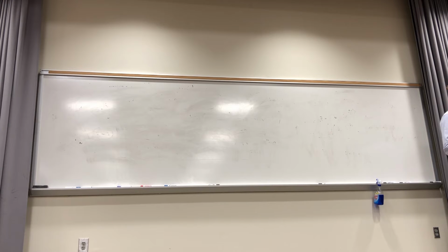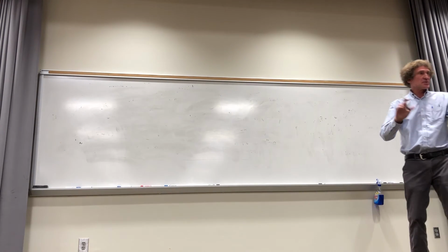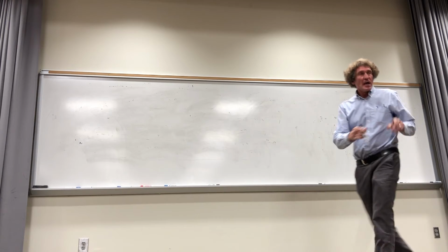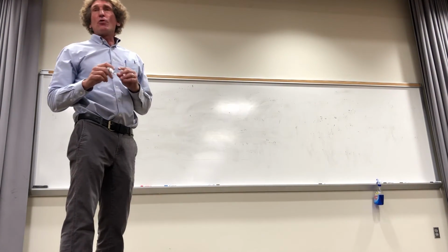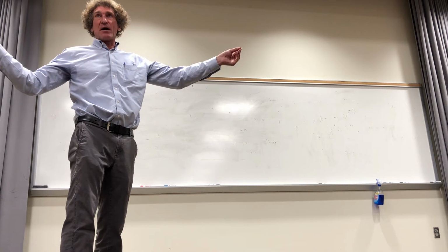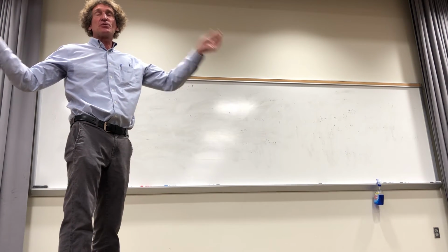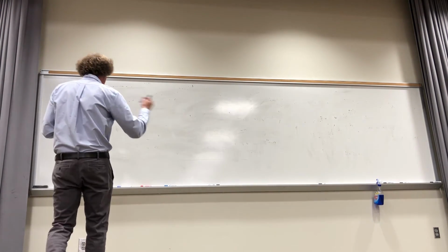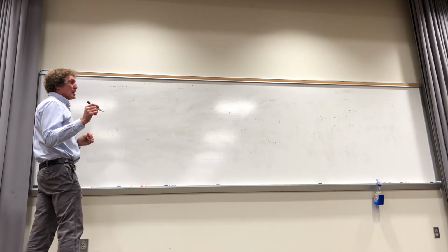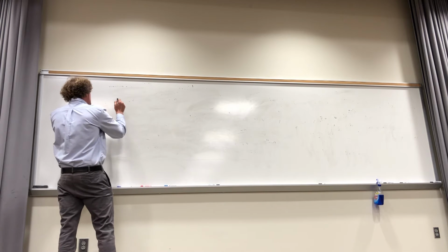All right. Do you feel that you can just handle a couple of problems with that on your own, if I give you solutions? I think you can. It's not hard. It's just an extension of something you already knew. And if you do it using cascading filters, don't write the whole equation down in terms of z to the 6. Just do individual difference equations. We know we're going to have one feeding the other. It's easier that way. The next thing is deconvolution.